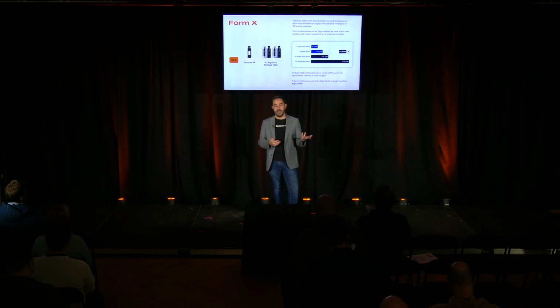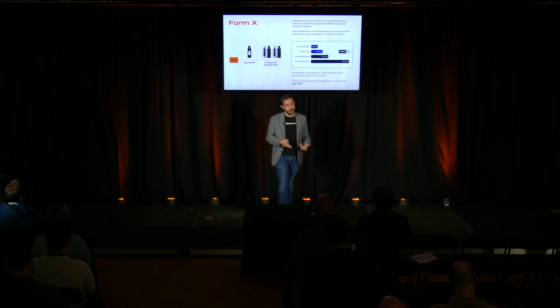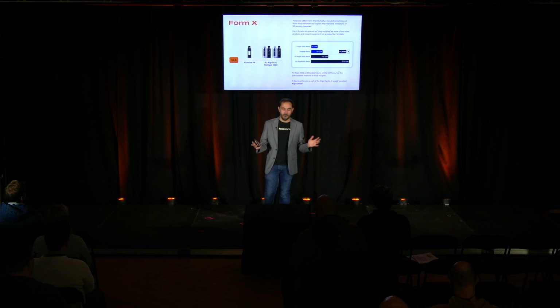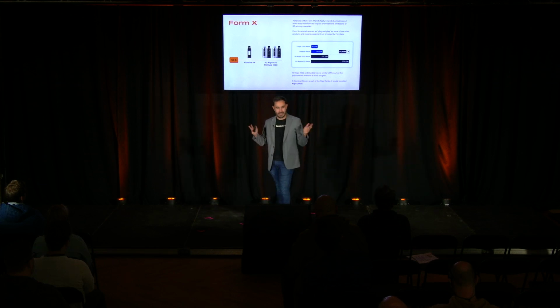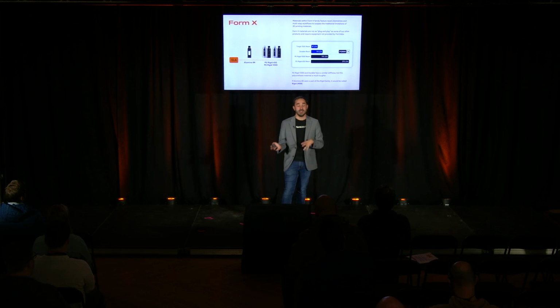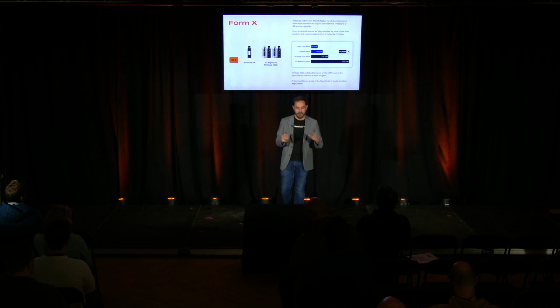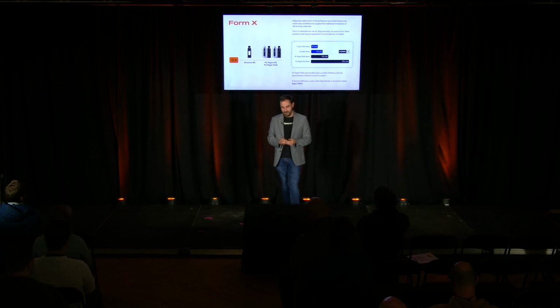Likewise, the fun anecdote I have for Alumina 4N is if we named it like we did for the rigid materials and used the elastic modulus in the name of the material, it would not be called Alumina 4N, it would be called Rigid 390K or Rigid 390,000 because that is its tensile modulus. It is just that much higher than a Rigid 10,000. It's higher than a stainless steel. It's a very, very stiff material because it is a ceramic at the end of the day, not a polymer. Awesome. So that is Form X.